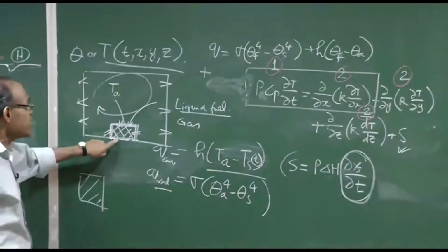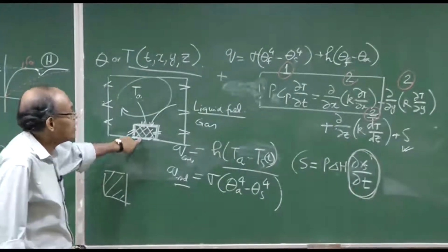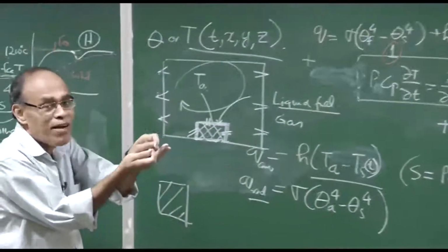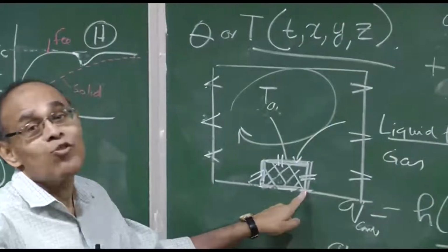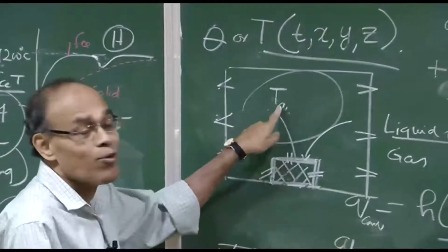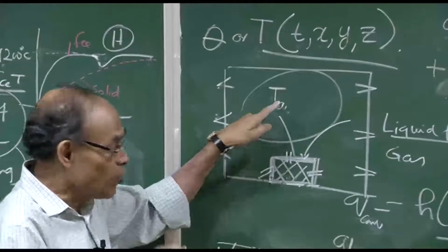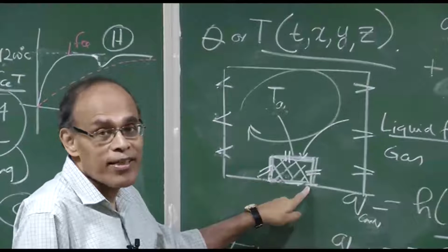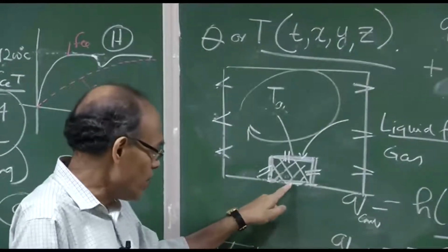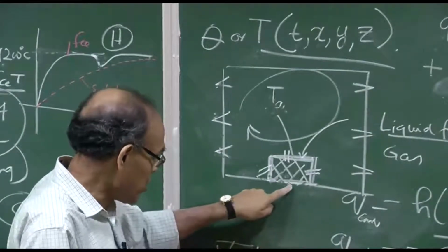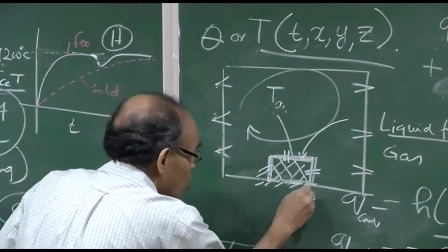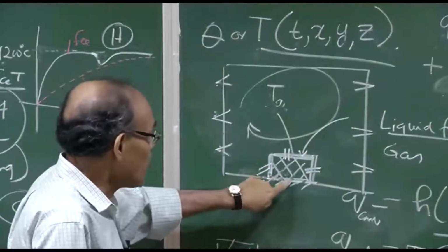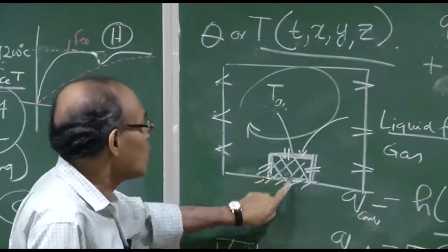On the other hand, the 6th surface is going to be heated differently. If there is a perfect contact between the refractory, you can say this surface temperature is going to be equal to the refractory temperature, which may be equal to the furnace temperature. Or if you want to do it more exactly, then you can take into account a contact thermal resistance between the two, because you know the furnace or bottom surface temperature, which is 1200 degree centigrade. If you add that contact thermal resistance, like an inverse of heat transfer coefficient, you should be able to find out the heat flux through this particular surface.